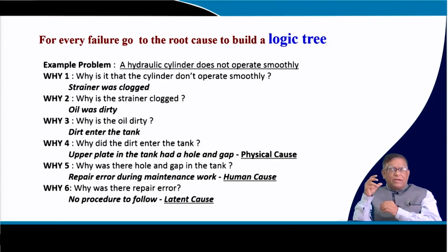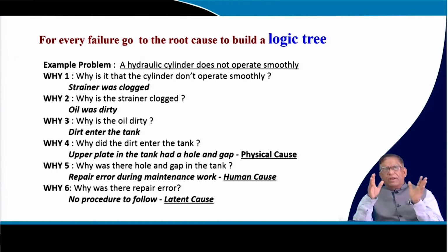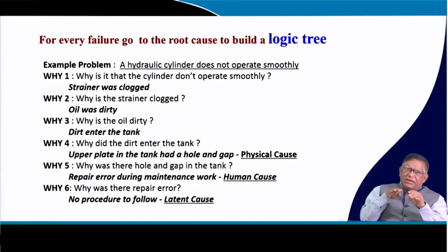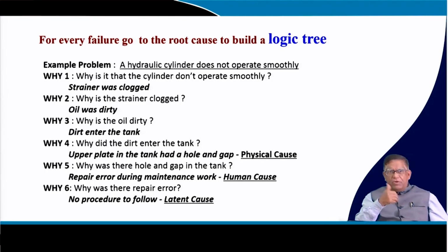But before going to what those languages are, the techniques by which you will be sensing the condition of the machine are also a part of it. Before that, when any problem comes, say for example in your system, whether it is a reclaimer or some of your vibrating machines, you may use a hydraulic cylinder. What is there in a hydraulic cylinder? The piston, it should give a linear motion properly. If it is not happening, you can first ask the question why. Why does the cylinder not operate smoothly?